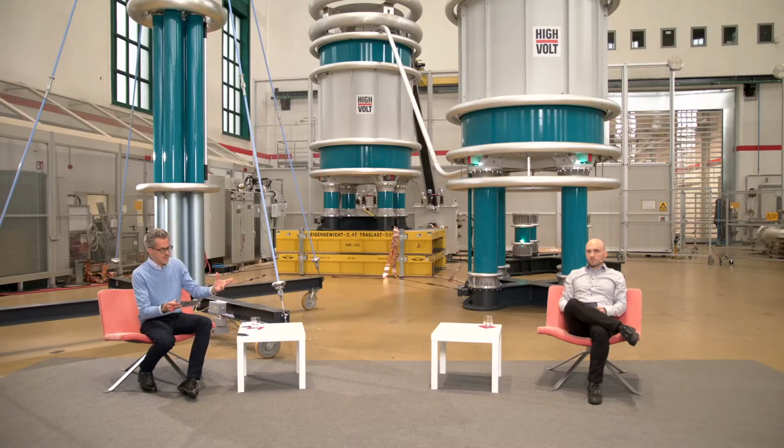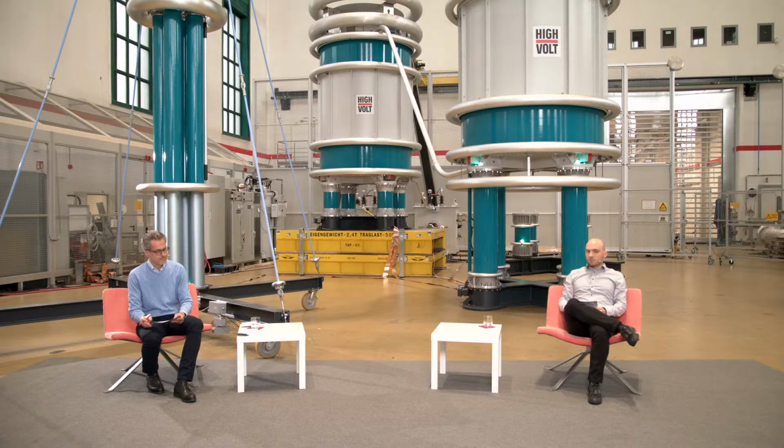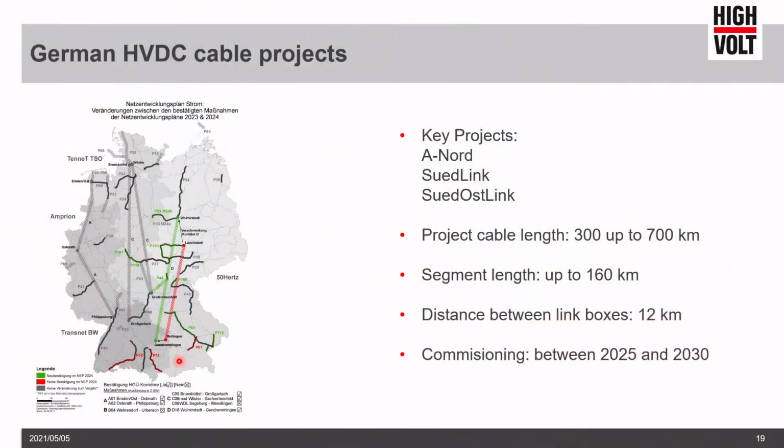Erik, very shortly about the cable, the big German cable projects here with several hundreds of kilometers of DC cable measuring each cable joint. What amount of data will be produced and how could you handle this? Yeah, if you think of a really high performance measuring system, which you have to use in this case to fulfill all the things I told, to find every signal below the noise, to extract better features, to enable more interpretation and characterization, you have like 250 mega samples per second. So that means 500 megabyte. I think everybody can do something with this number, 500 megabyte at least per joint.